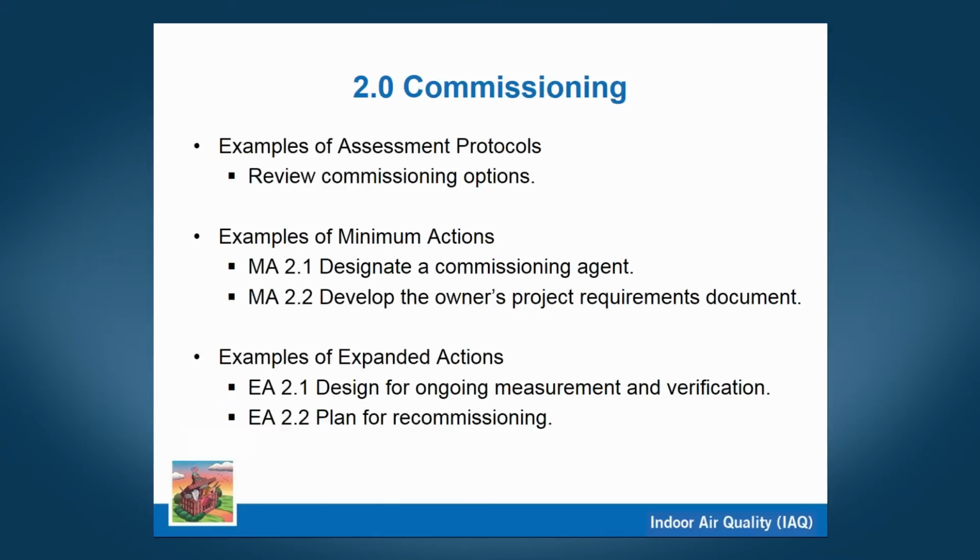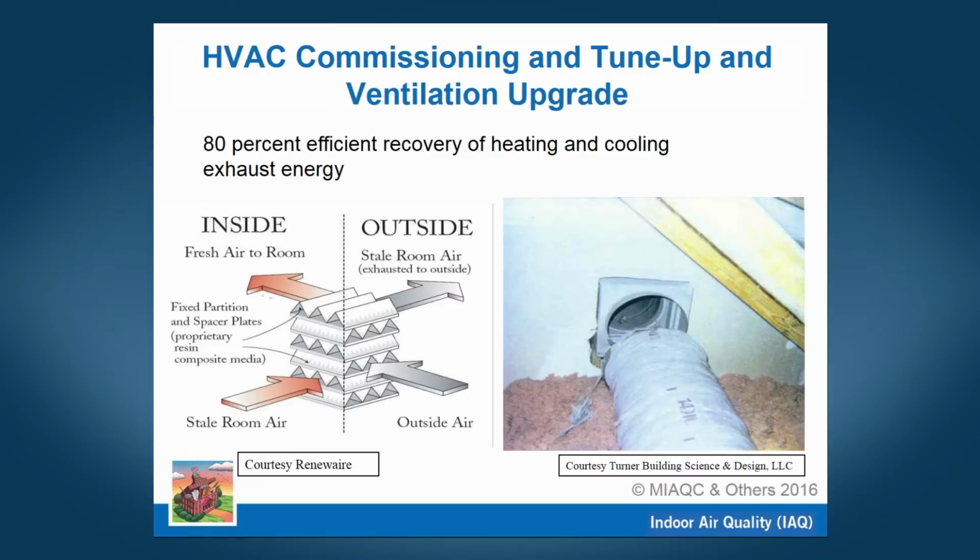You can find more information on commissioning also under Appendix A of the guide. A normal part of renovation or energy upgrade would be to do an HVAC tune-up, go find equipment that's not running as intended, whether it's a duct that's no longer connected, or a fan that's not turning, or a belt that's never been there.